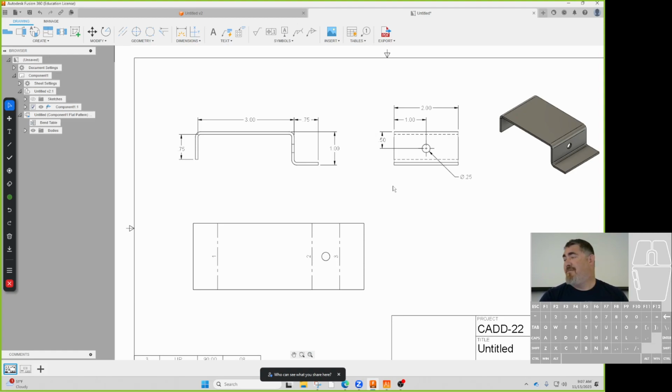So they're going to drill it in. I'd rather check it here, after it's bent. Remember, the drawings are for checking, so I'd rather check it here to verify it's in the right spot. So my rule is I dimension down here with ordinate dimensions. I'll go here, and I can just pick.